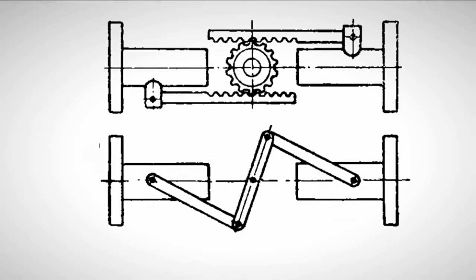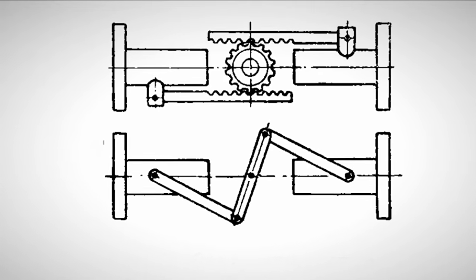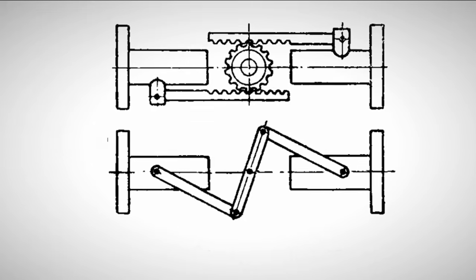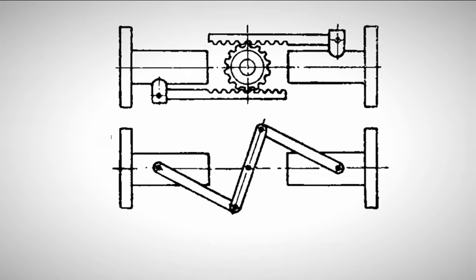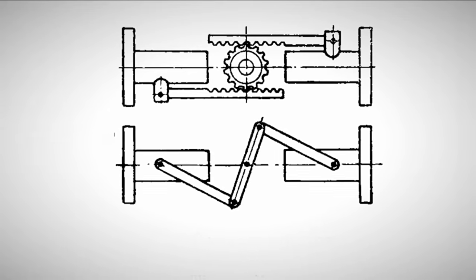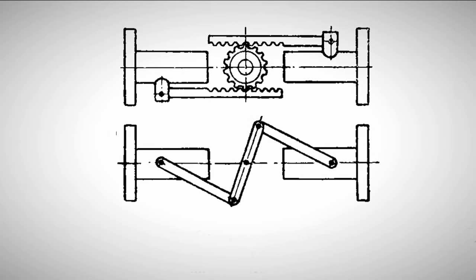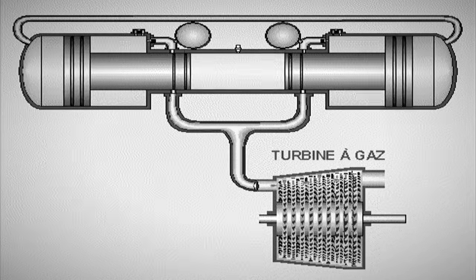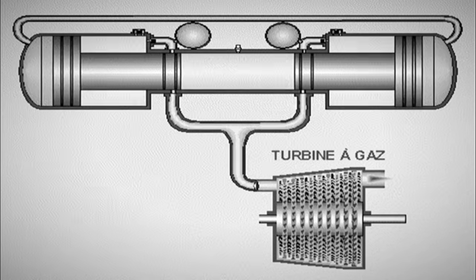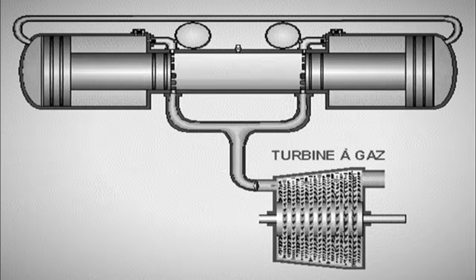To ensure that both pistons operate synchronously and reach their extreme positions simultaneously, they are linked by a special rack and pinion synchronizing mechanism. Although a crankless engine can operate without this, its pistons will move freely under the action of gas pressure and air buffer, but in this case, even a small deviation in the synchronous speed of one of the pistons can disrupt the working process of the machine.